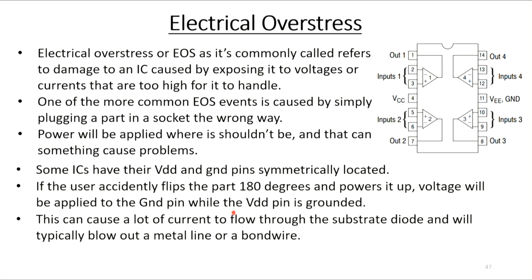Switching topics again. Electrical overstress, or EOS as it's commonly referred to, is damage to an integrated circuit by exposing it to voltages or currents that are just too high to handle. One of the more common EOS events is caused by simply plugging the part in the socket the wrong way. You can apply power where it shouldn't be, and that can sometimes cause problems.